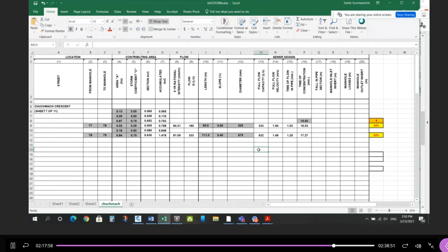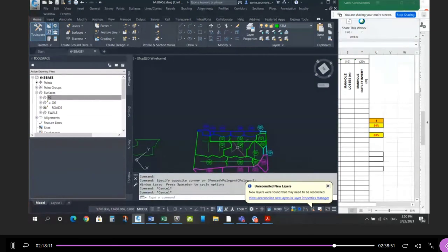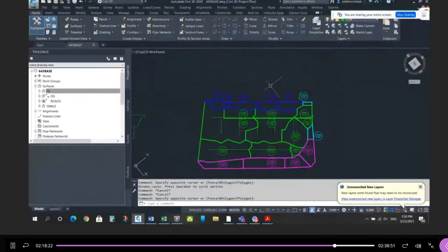And this is what you have to show the municipality, because that's what you're proposing to do. I'm going to take the backyard of these townhouses, these blue areas, and I'm going to put them through this sewer. And that now puts less area through our site. So the pipe that's here now is probably too big because there's less area going there now. So this is all theoretical discussion when you look at the drainage areas, right? Can I take the area that way?